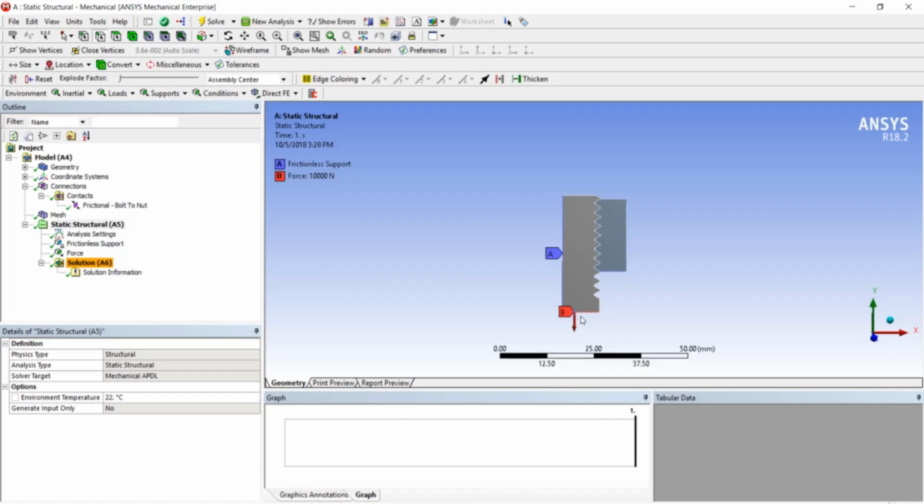So if you have a pressure value and you need to convert into line pressure value, what you need to do is you just multiply this pressure value by the area on which you want to apply, and that value which is going to yield is the value which you are going to apply as a line pressure instead of an area pressure.